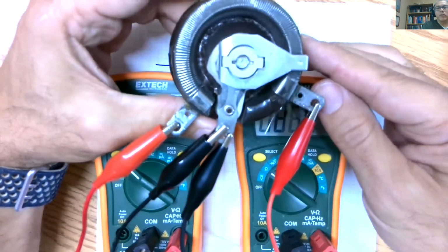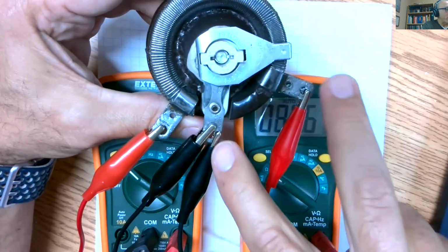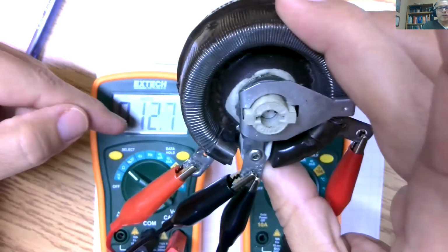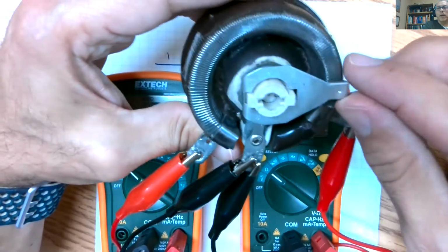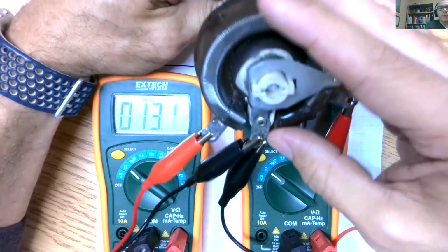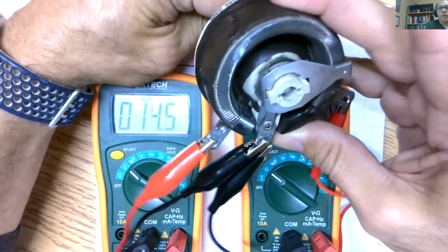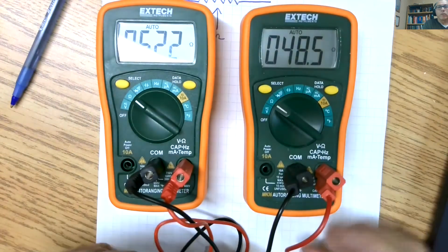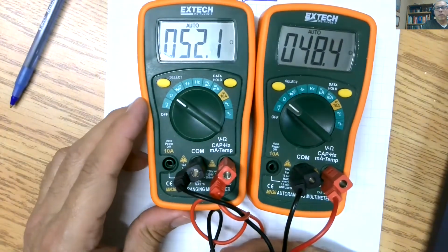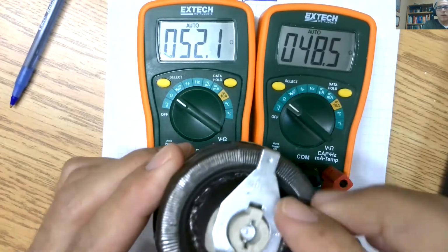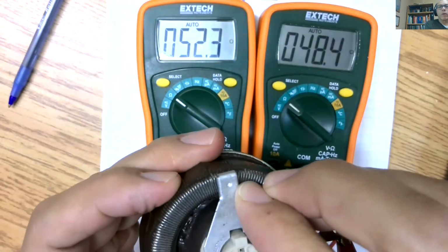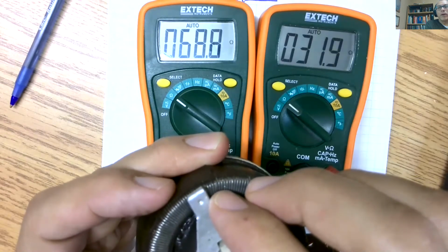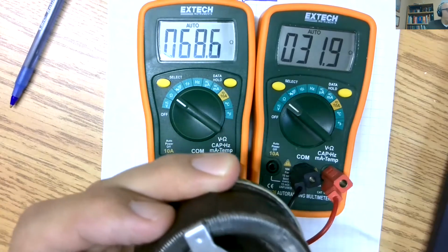So here's my resistor. Right now, the resistance between these two pins, which is on the meter on the left, is very small because the wiper is very close to that pin. As we move the wiper away, this resistance increases and this one is decreasing. So I'm just going to move it up a bit so we can view it all at once. Okay, there. So as I move it, the resistance changes between the two pins, but it always adds up. Right now, 68 plus 32. So we have our 100.